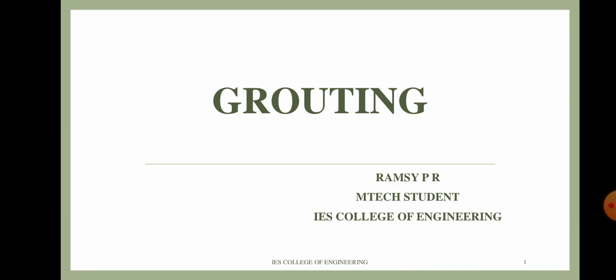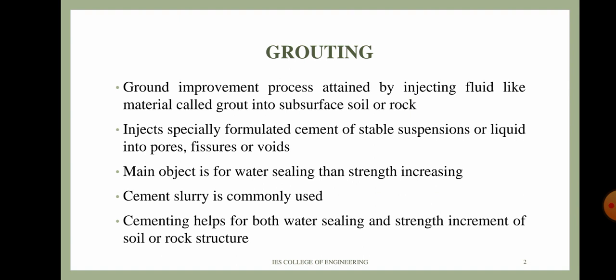Here I am discussing the topic grouting. Grouting is a ground improvement process or technique which is attained by injecting fluid-like material called grout into the subsurface soil or rock mass of the ground. Here, a specially formulated cement of stable suspensions or liquid is injected into the pores, fissures or voids of the ground. The main object of the grouting is water sealing, then strength increasing.